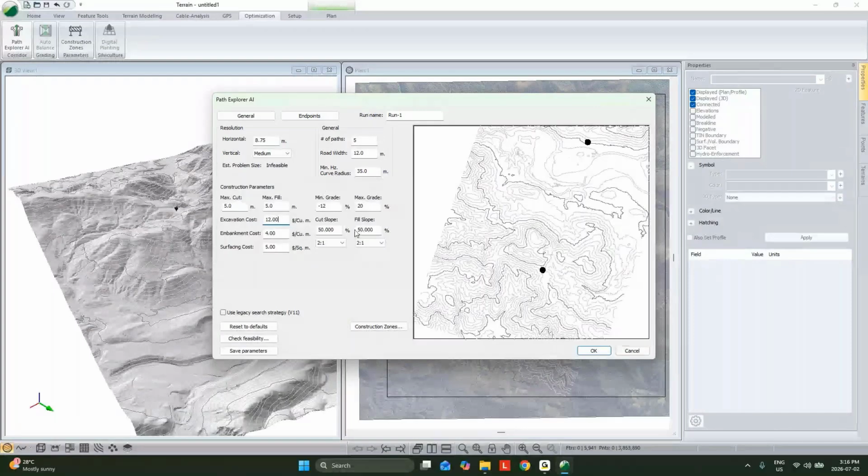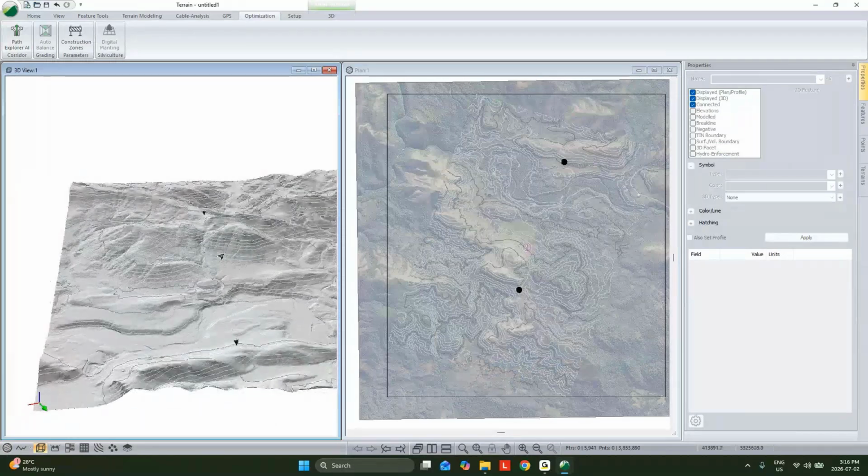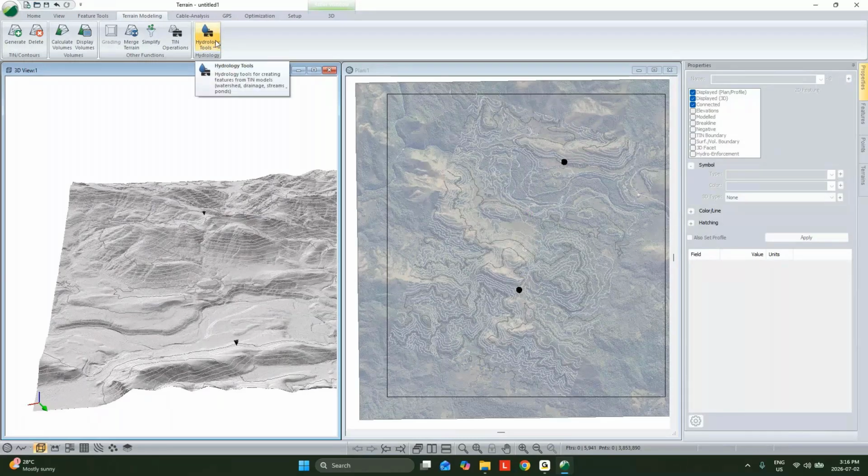But aside from just dirt, there's going to be some other things that we want to consider here. And those other things could be, well, maybe there's a sensitive site where we're worried about terrain stability. So we could add in a polygon or draw in a polygon and say, well, I don't want to go there. The most common one is going to be accounting for where water is. So whether those are streams, ponds, etc., we probably will want to have at least some consideration for that, unless we were doing an entirely ridgetop road.